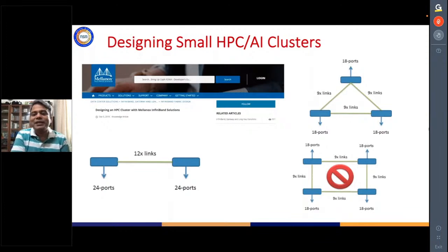One of the simplest limits is the die size. You take a large wafer, and to get a good yield, you will have a certain size of die on it. A certain size of die will be able to service only a certain number of ports, because finally you need to take electrical signals out of that die. How many ports you can take out of that die depends on how many pins or ball grid arrays you will have from that silicon.